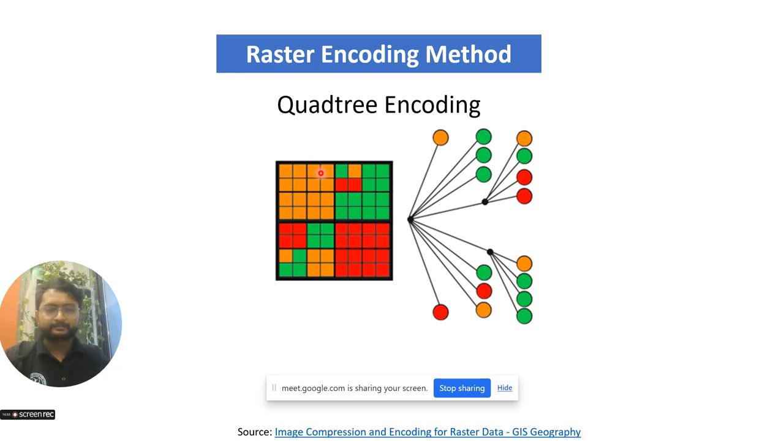Sir, if I can explain, when images are taken from a satellite, since the Earth's surface is curved, or what we call a spheroid, and when we superimpose that image in GIS, we are superimposing it on a 2D analysis platform. So in order to relate the image obtained from the satellite to that, we need georeferencing. Yes, that is one of the reasons.